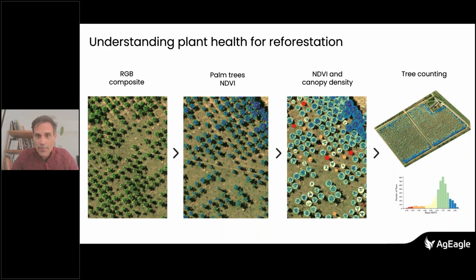You can also go to our website. If you go below, on the lowest part, you have the MicaSense Flight Calculator. Very interesting. Here you can say, okay, I have 100 hectares. I want to fly at 100 meters altitude, with a fixed wing, at 50 kilometers per hour or meters per second or miles per minute, whatever units you're using. And it gives you how many pictures you will take, how many gigabytes of information you will have, because these cards only have 128 gigabytes. So that's the limit of what you can do.